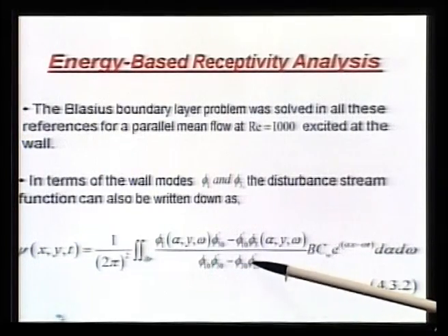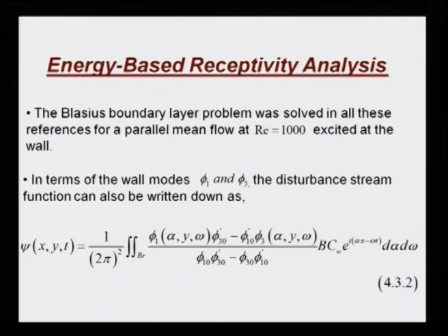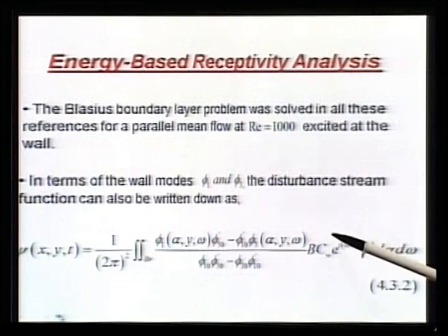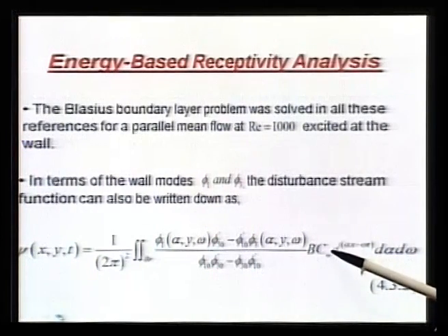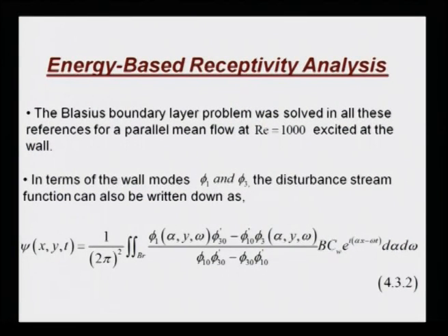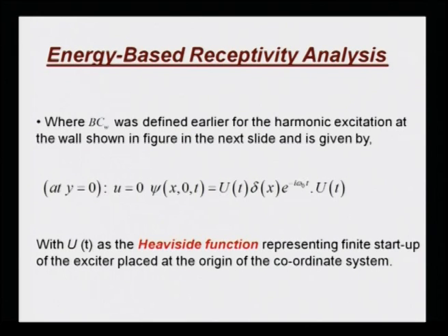This is how we coupled the receptivity and the stability equation. In addition, this condition BC subscript w tells you how exactly the shear layer has been destabilized from the wall. So, that is essentially a boundary condition coming from the wall. We can have various formalisms of this quantity that we have already seen.